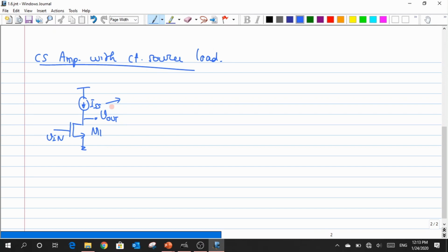NMOS? Okay, so let us go with the NMOS, but because the source terminal of the NMOS has to be lower than the drain potential, right? So whatever source potential I have has to be smaller than the drain potential for an NMOS. So if I do so, what happens is that whenever there is a swing at the output, what is happening across the VGS of this M2 transistor? The VGS is varying, which means that the current is no more constant. I cannot use that. Okay, so then what type of MOSFET can I replace for this ISS?